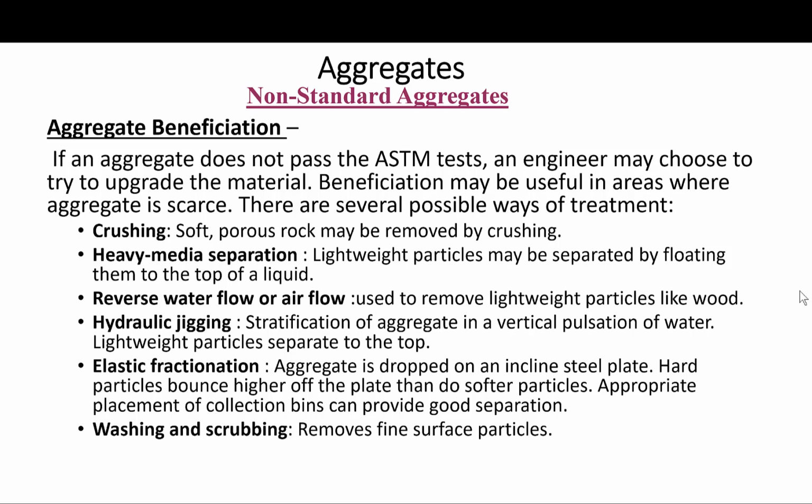Again, the aggregate in this case is dropped on an inclined steel plate. The hard particles bounce higher off the plate than do softer particles. Appropriate placement of collection bins can provide good separation in this case. Washing and scrubbing removes fine surface particles.